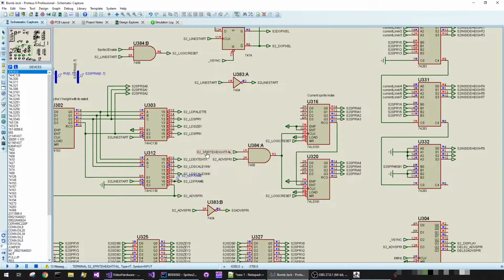If the sprite height test fails, in other words it early outs the sprite rejection test, or we have finished stamping pixels from the sprite to the scanline, then this triggers the sprite index to be incremented.